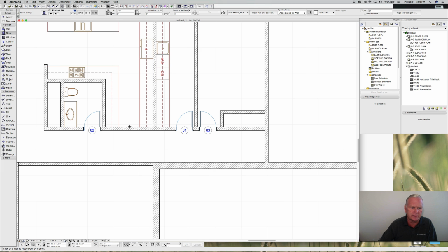And now I want to put this in the center of these 2 edges of the countertop. So I'm going to click the center insertion point method, and you'll see a tick mark coming up over here for center of this entire wall. So at this point in time, we want to slide down here and change that special snap point to be the multi-point, and then come back up here and you'll see our tick mark come in. You see the little check mark. We'll click once for the pocket door. Now we can decide which way we want the pocket to go. Click on it again, and the door is in place.